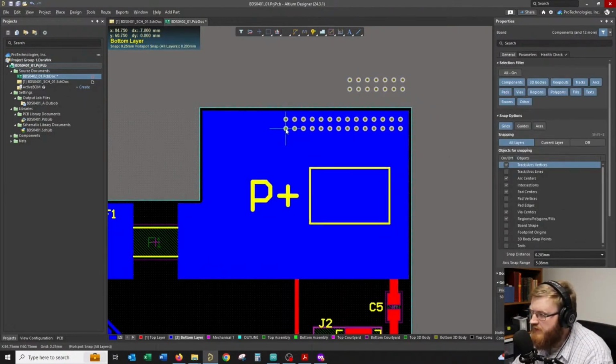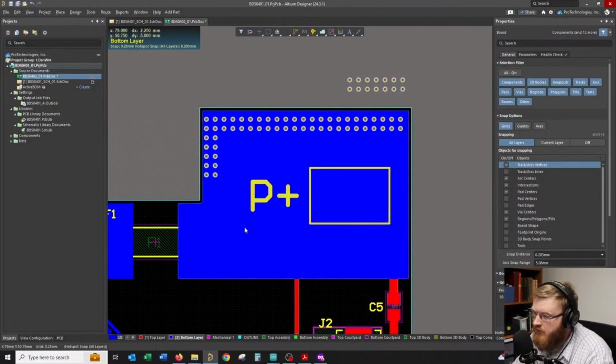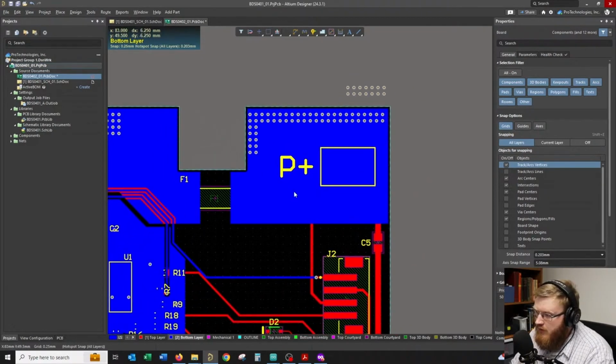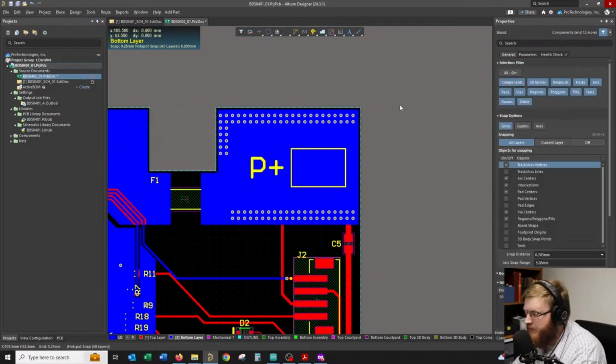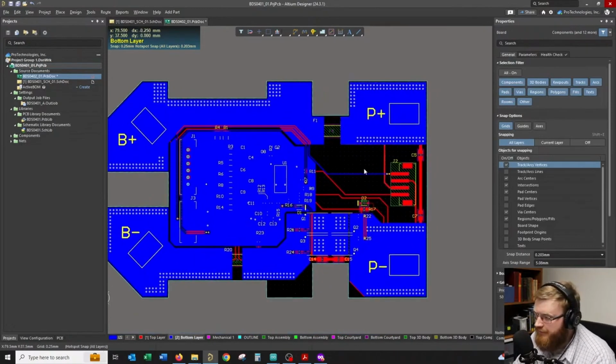So when you move vias, they keep their original properties, so you can't just move them like I just tried to do, or else it won't couple to your copper pour. Okay, so let me throw some down along here. Again, not for electrical, just for some thermal.